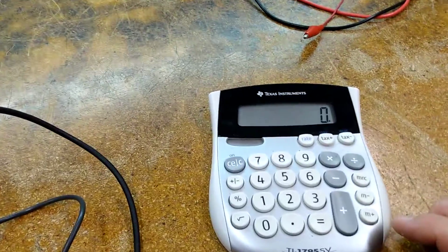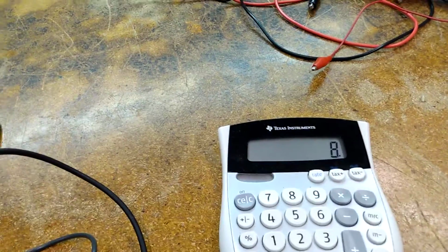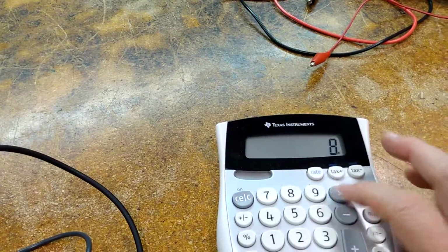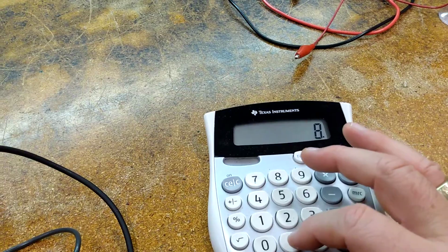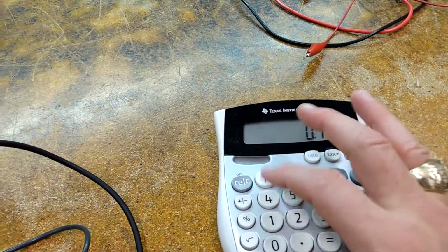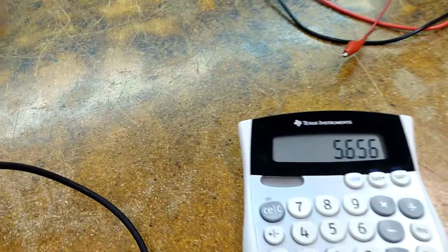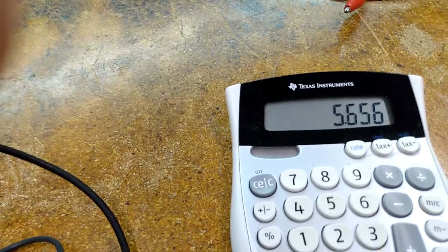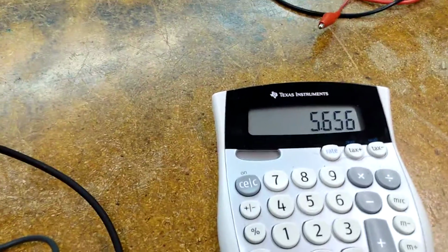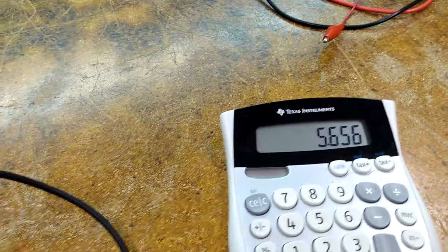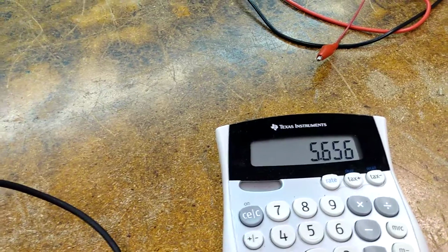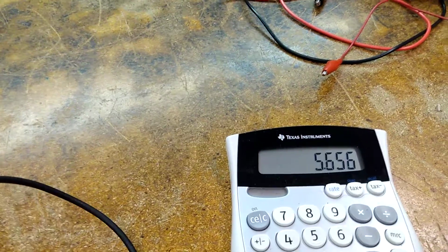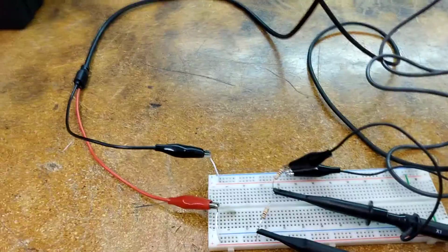If you remember your calculations, let's take our 8 volts, multiply that by 70.7%, or times 0.707, and that equals 5.656. So 6 volts was an easy number. 6 and 8 volts are easy numbers to look at. You're always going to have a decimal piece in there, but it was easy for us to take 8 volts peak to peak and compare it with 6 volts DC.